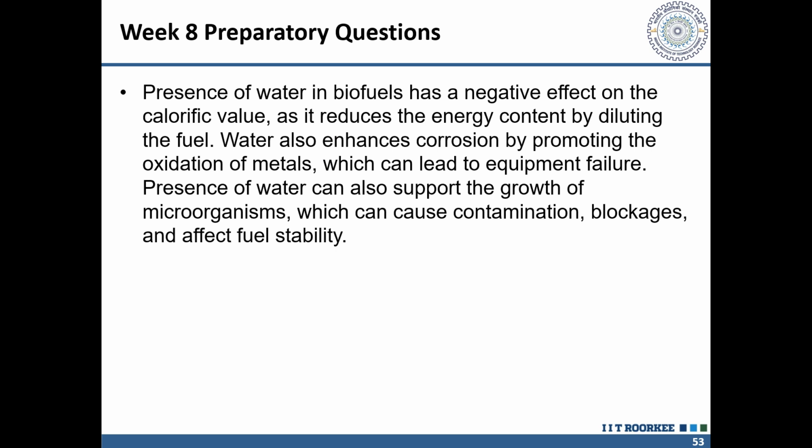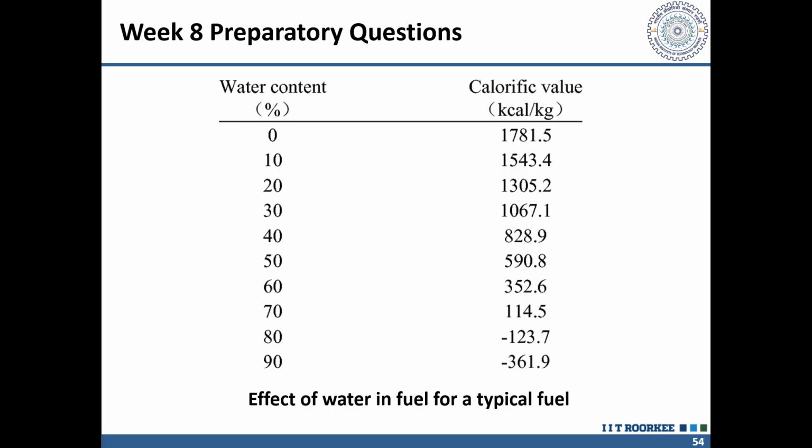Now we have seen that presence of water in biofuels has a negative effect on the calorific value, as it reduces the energy content by diluting the fuel. This is a table that shows how water affects the calorific value. If a typical fuel has a calorific value of 1781 kilocalories per kg, then with a 10% increase in water content, the calorific value decreases. So as the content of water increases, the calorific value decreases.